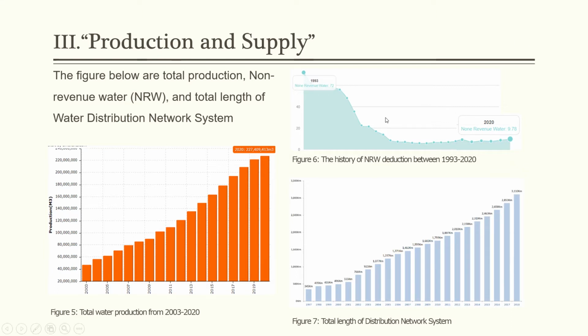The decrease came first from the support of experts from Japan, who cooperated with the Phnom Penh water supply staff and continued to control non-revenue water in Phnom Penh city by using equipment like listening bars or the DMA, district meter area, supplying block by block.